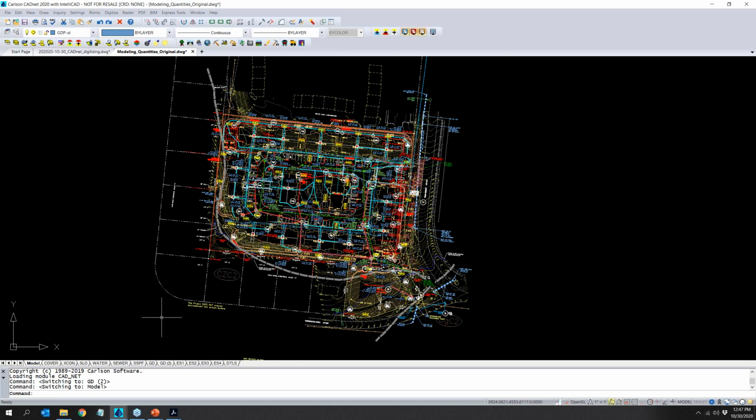So let me just make sure that you understand. If you are doing this for estimating and takeoff purposes, you're going to end up most likely with some cleanup that needs to be done in your drawing, and you're going to end up with some elevating that needs to be done. You're going to have 2D entities that, to get accurate surface models, to stake by or to get quantities from, you're going to need to elevate.